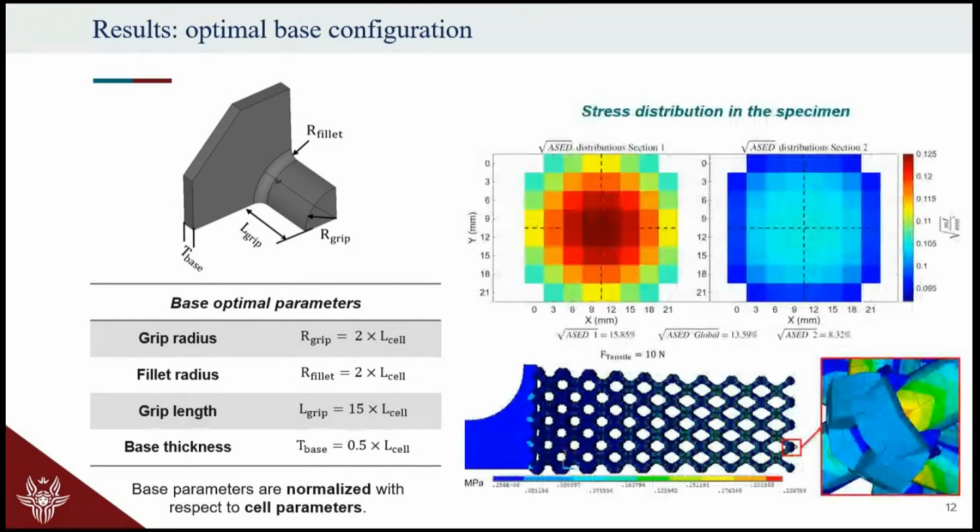And once we have done this, of course, we can take also a look at the stress distribution. So this is the average strain energy density distribution over the cross-section. If we look at the von Mises stresses, for instance, here, you can notice that we have very low stresses nearby the transition between the solid material and the porous one, while we have an increment of the critical stresses nearby the gauge location, and you can also visually inspect the fact that they're almost the same. So we reach also an isocritical stress in this location.